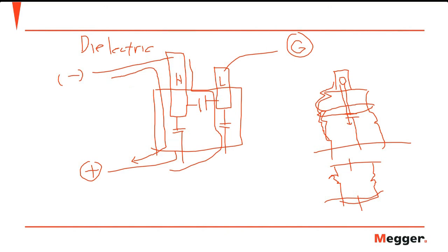If you don't have that, you can actually use a bare copper wire or any bare conductor. That is good. However, we avoid that because sometimes it can scratch and damage the insulation, but it is the best material to use for guarding. You can use a bare conductor, and then you can have the guard here.